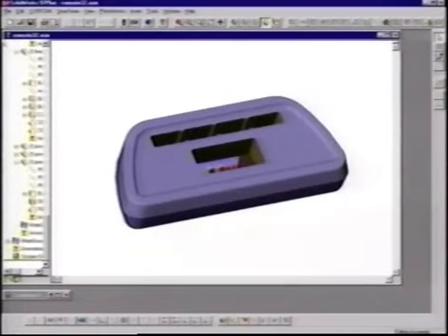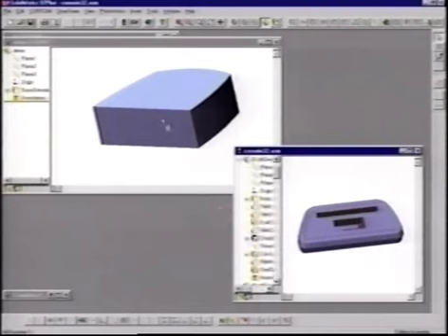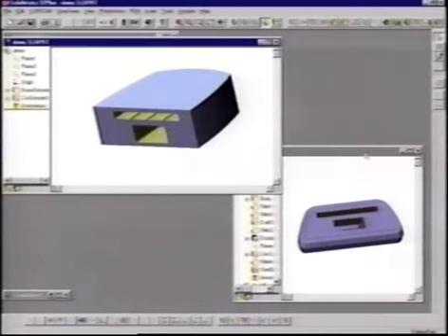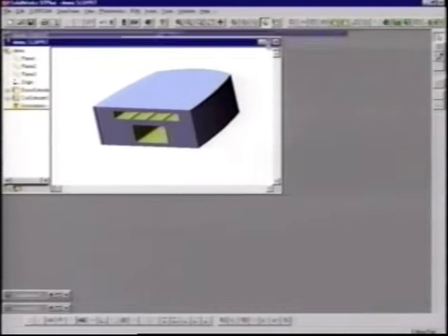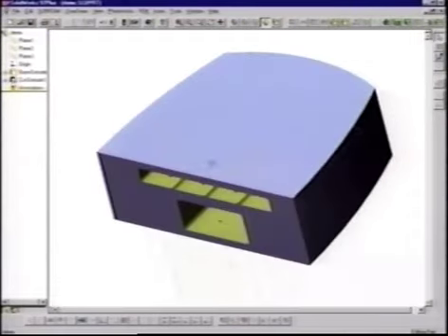Now that that assembly is inside of SolidWorks, let's take advantage of that console cutout that we see in that assembly in the part that we're working on right now. Now one thing to remember is SolidWorks is a native Windows application, and when you work in the Windows environment you're accustomed to certain types of interaction, such as dragging and dropping. And that's exactly how Joe copies that feature from one part to another. Notice the preview that SolidWorks gives you, so you see exactly what that feature is going to look like on the part before you release the mouse.